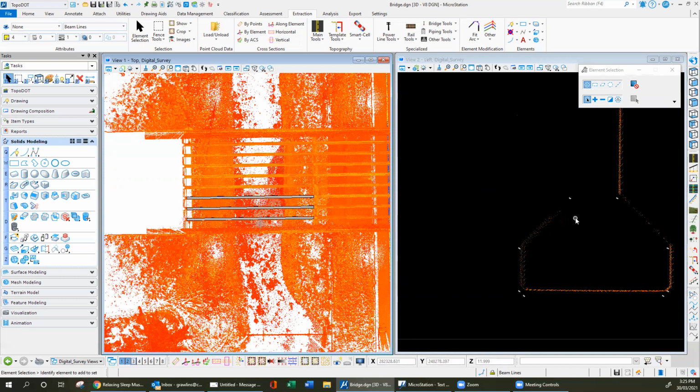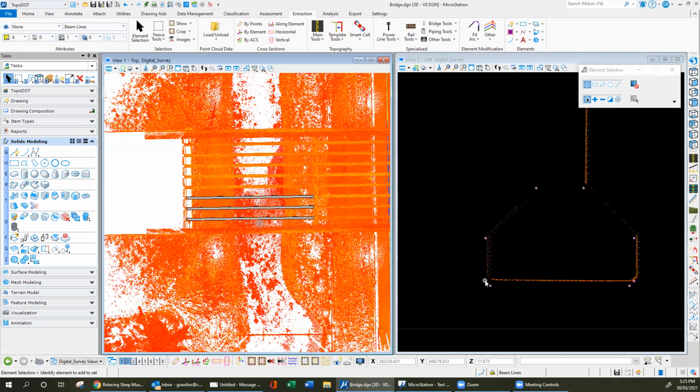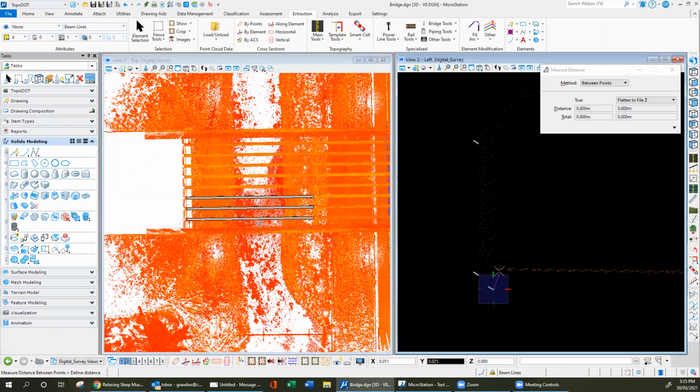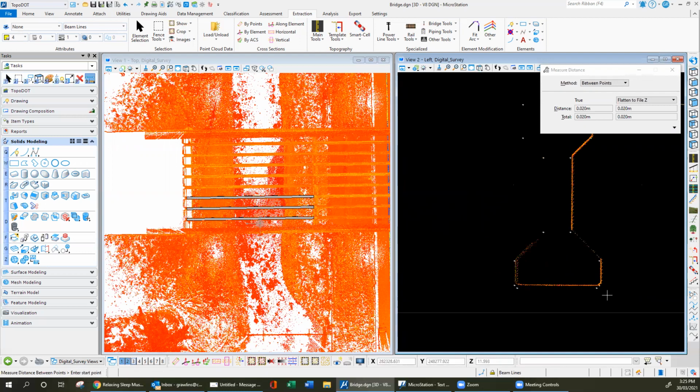We can see that even though they're perfectly lined up or aligned at the ends of the spans, we have now got some discrepancies through the middle here, and these beams are exhibiting not only a vertical arc or curvature, but there's also a slight amount of horizontal as well. Let's just pop a measurement on that. So vertically, we've got 30 millimeters out. Horizontally, we've got roughly 20 millimeters out. So with the curvature of those concrete beams, this method hasn't suited for mid-span.